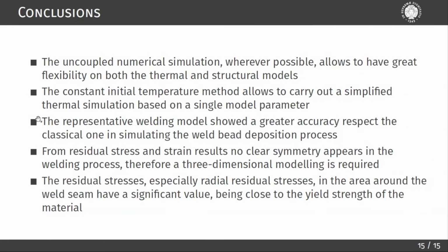To conclude, I want to highlight some interesting points. First of all, the use of an uncoupled formulation gives great flexibility for this kind of simulations. Having an uncoupled formulation, it is possible to decouple thermal and mechanical analysis. In the thermal part, a constant initial temperature method is used. This model allows to set only one parameter in order to work properly.